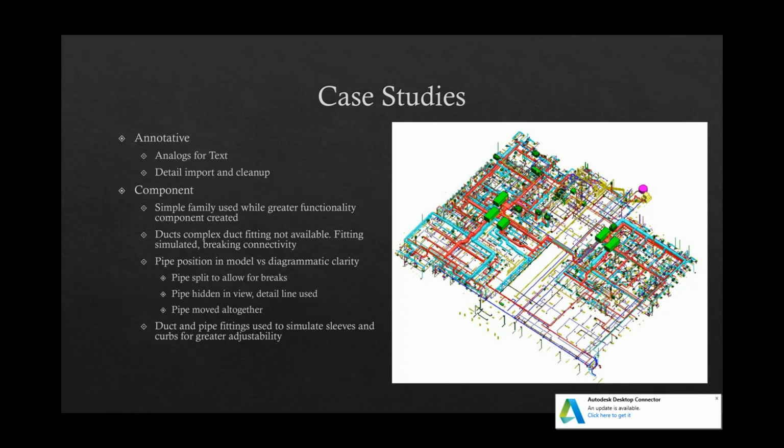And for smaller scale ones where they probably won't get to that level of detail, it's okay to place Revit pipes, the actual families, as they are stronger than just making lines, but in a more diagrammatic fashion where they might have some clashes to them, but if it's not being coordinated for your job, then that may be acceptable.